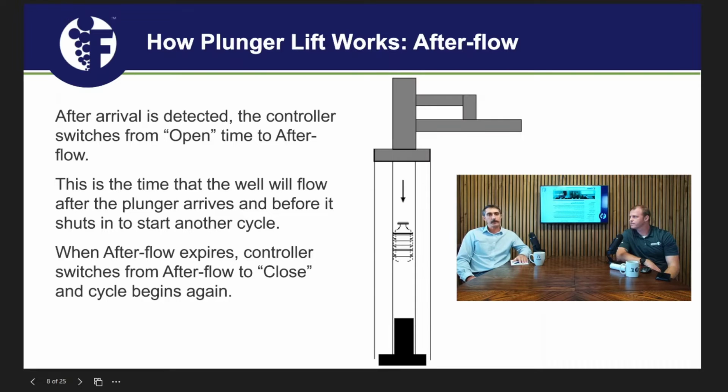With a bypass style plunger, when it hits the lubricator, whatever bypass mechanism you have, whether it's a ball and sleeve or a dart, has shifted back open, so it could potentially fall during that afterflow. I prefer in that case to have an auto catch on the lubricator so that we're controlling the fall, just because that helps us get better data in the future. And that auto catch is a feature that you add to a lubricator. Absolutely.